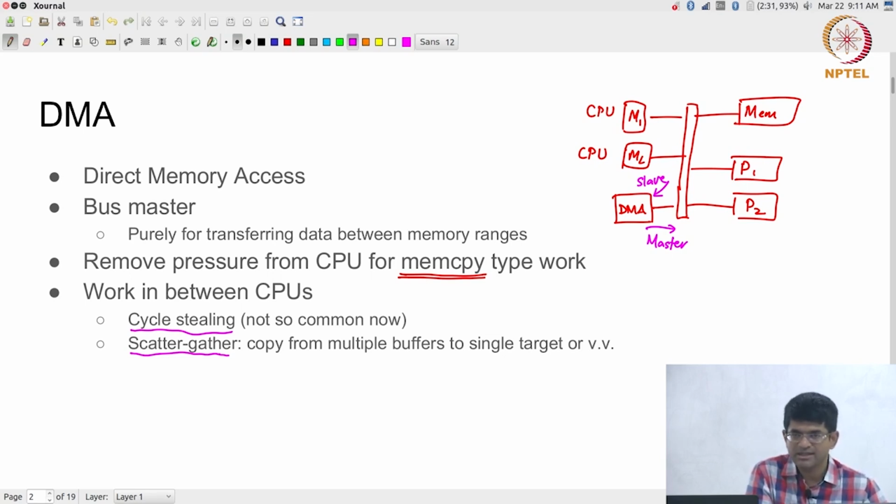For our immediate purposes, the main thing that you need to keep in mind is, for your projects, you will notice that the AXI Lite interface, which was part of the FFT code that I used for the demo, is painfully slow. Right? We saw in the demo that the data transfer ended up taking 10 times as many cycles as the actual computation. Out of the total of some 35K or 40K cycles, the data transfer accounted for about 35K. Nearly 90% of the time was spent in that.